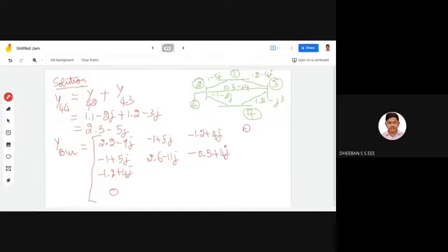Okay, and then y24 is -1.1 + 2j. After that, by the symmetry property, you can take it out to this side, so it will be -0.5 + 4j, and over here it will be -1.1 + 2j. For your y33 it is 2.9 - 11j. Okay, and your y34 is -1.2 + 3j, so you can make it symmetrical,